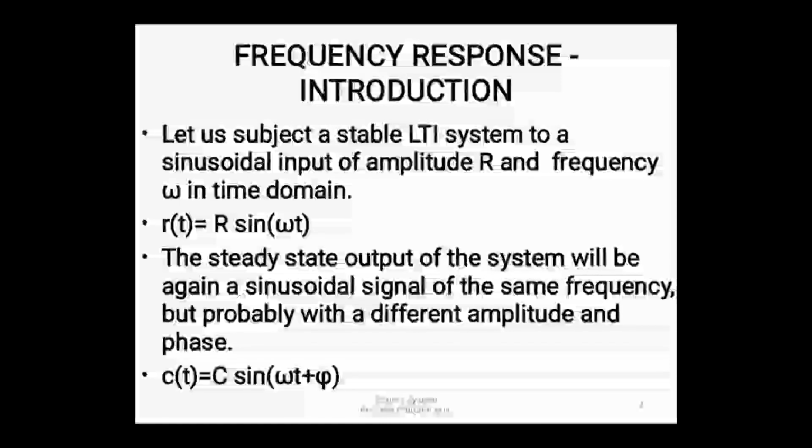The steady state output of the system will again be a sinusoidal signal only, having the same frequency but a different magnitude or amplitude and phase. So the output c(t) is equal to capital C into sine of omega t plus phi, where capital C is the magnitude of the output and phi is the phase angle.